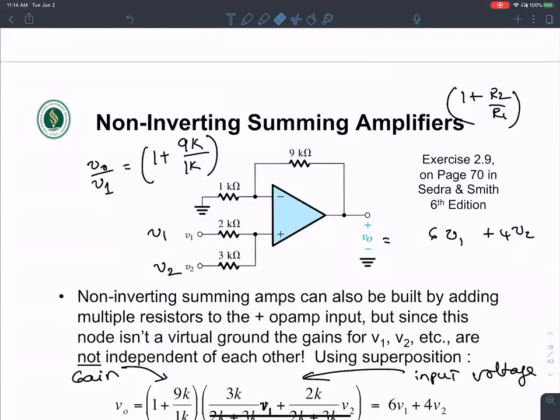Okay, so I have a question in the chat that says, any pre-lab calculations or simulations for lab 2? There is one circuit with a diode for the second lab. That's the only thing that you need to do the simulations on. It's the transient analysis for a circuit with a diode: you apply a triangular wave and see how the upper part of the triangular wave is passed and the lower part of the triangular wave is cut off by the diode.